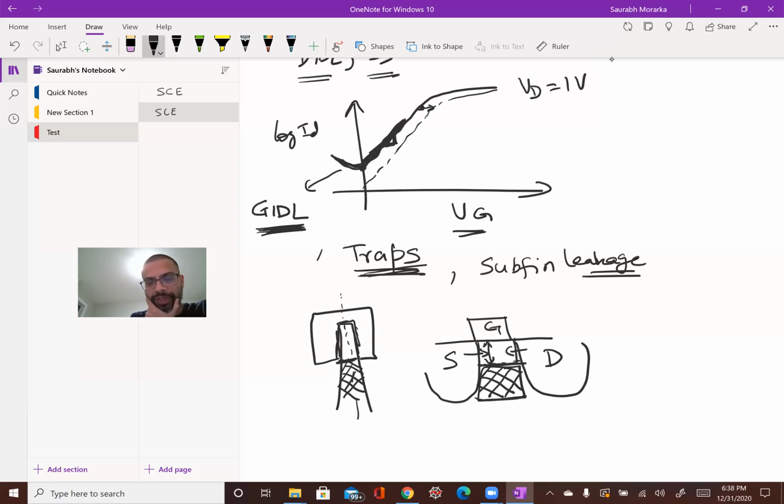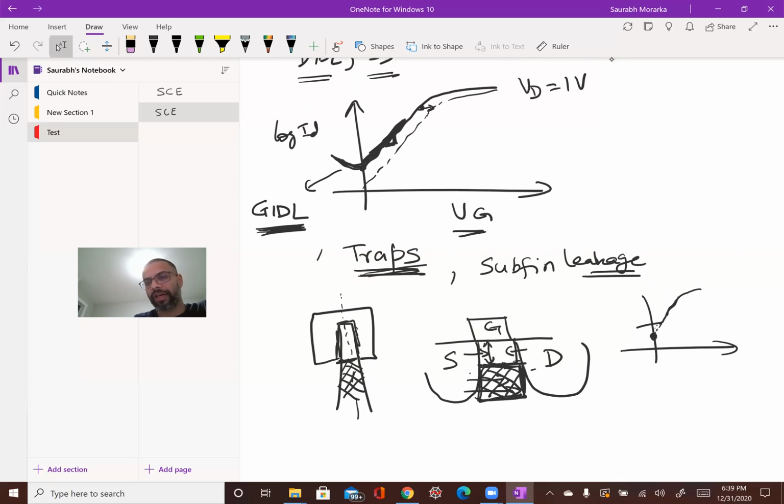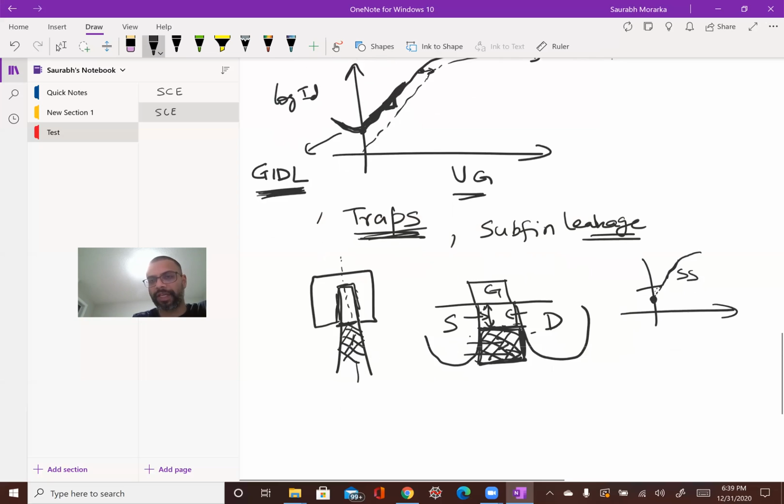However, in this cross-hatched area, the source and the drain are free to talk to each other because the gate has no control. And this leakage is one of the most painful things to control in a FinFET, and that is one of the things that can impact the subthreshold slope. The subthreshold slope was coming down nicely and then it just flattens out, which means it doesn't end up reaching the leakage that it needed to reach because some current just kept flowing through this part. Correct? This is one of those things which affects the subthreshold slope much more than it affects the DIBL.